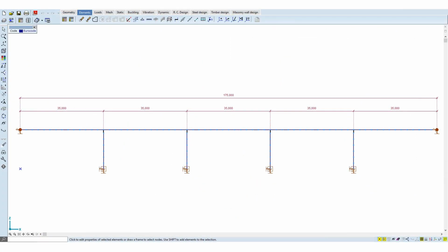In the next step, we will analyze the bridge with nonlinear behavior. In our example, the fixed pier capacity is not sufficient for such large bending moments. Assuming that this is an existing bridge, seismic mitigation methods can be effectively used to reduce the seismic actions on the pier. We will use an isolator on top of the pier to partially decouple the movements of the deck